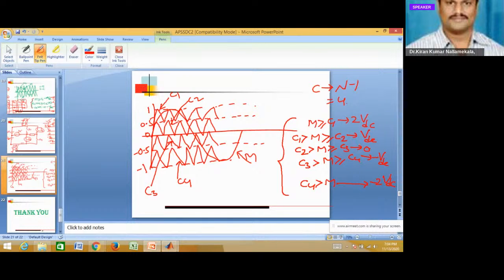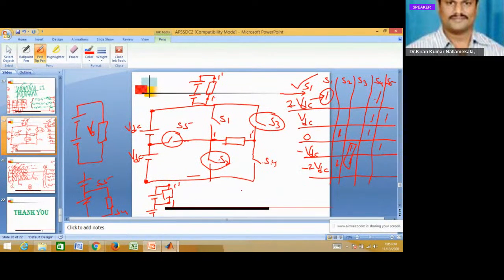First we will see how we generate these logics using MATLAB Simulink. Before that, we will generate this sine wave and 4 triangular waves first. This is step 1 and this is step 2, and step 3 is addition of different gating signals. Adding the different voltage levels to give to the particular switch.